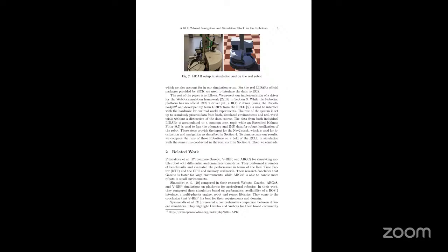Localization. Based on the position given by the extended Kalman filter EKF, with AMCL localization, we can locate where the current position of the robot is in the map. So now the current position of the robot is here, just imagine. After doing the localization, Nav2 will take the current position, goal, path planning, obstacle avoidance, navigation.